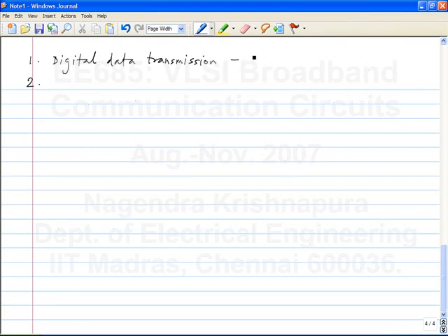Then basically look at how transmitters and receivers are built. And then you may have to change the rate of the signal, meaning you have two signals at 1 gigabit per second. You may want to combine them and send it on a single link at 2 gigabits per second. The reason for doing this is again the size of the infrastructure, right? So you can always send data at low frequencies. Let's say I initially said sending data at 1 gigabit per second is difficult, but that's okay. I'll have 100 pairs of wires and I'll send at 10 megabits per second. Then there will be no problem. That is true. It is true that at 10 megabits per second the transmission line may work perfectly, but the problem is now you need 100 pairs of wires. So that is the disadvantage.